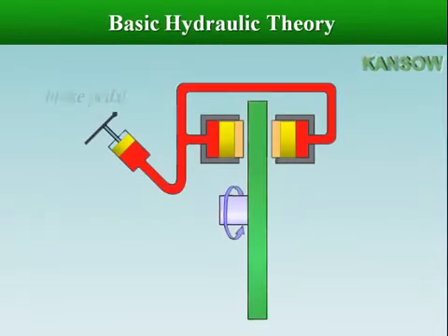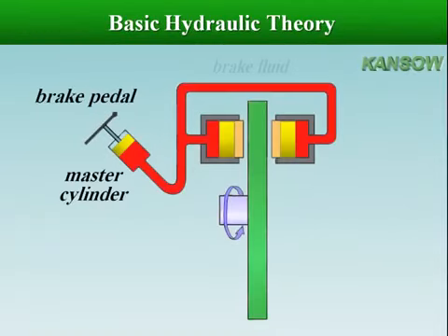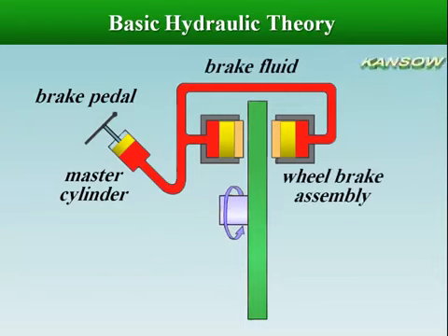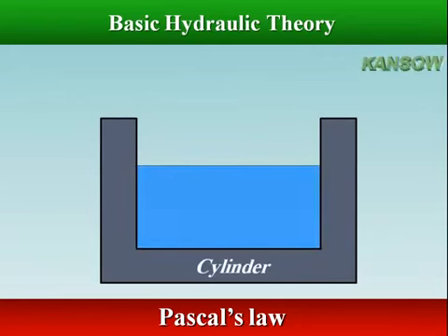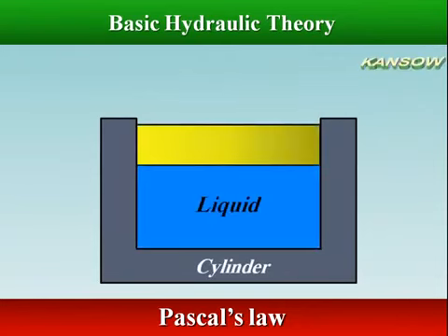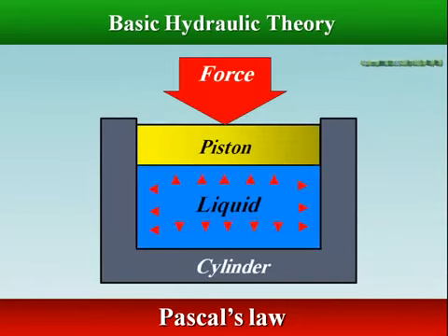Brake systems use hydraulic fluid in a closed system. The hydraulic brake system is governed by physical laws that make it efficient at transmitting both motion and force. Pascal discovered the scientific laws governing the behavior of liquids under pressure. Pascal's law states that pressure applied anywhere to an enclosed body of fluid is transmitted equally to all parts of the fluid.